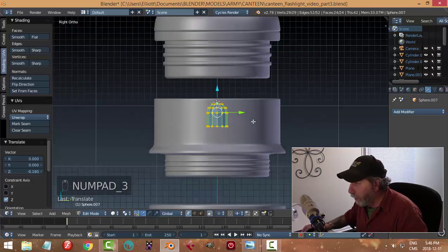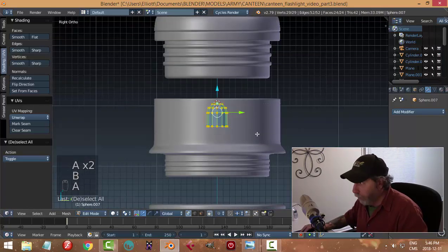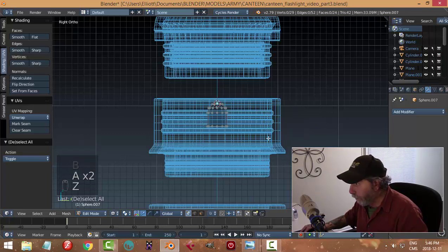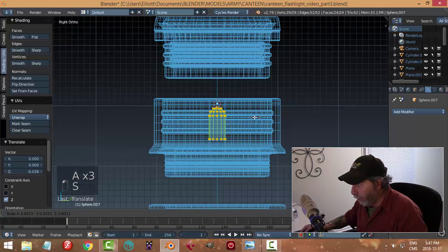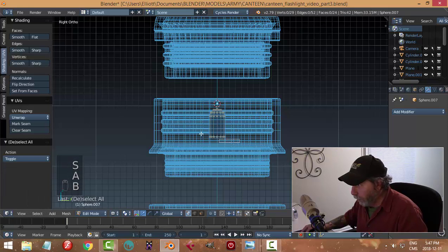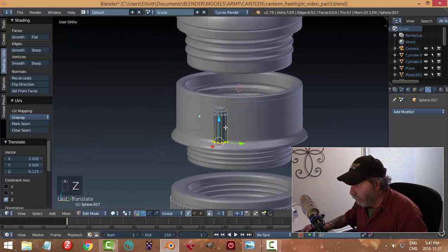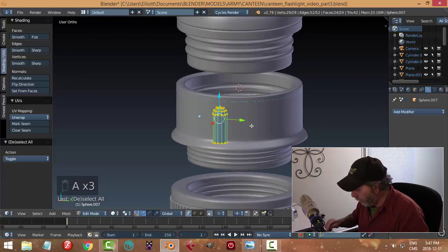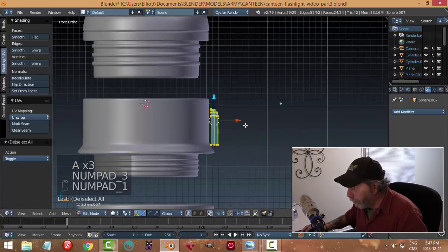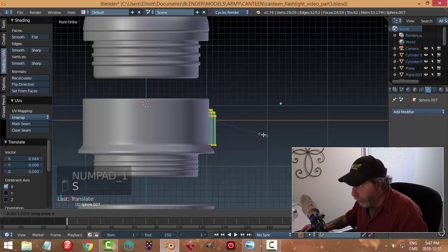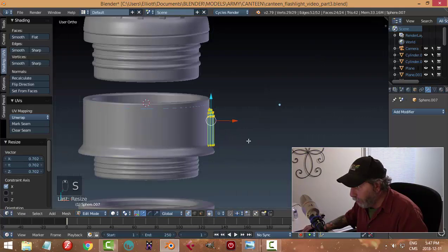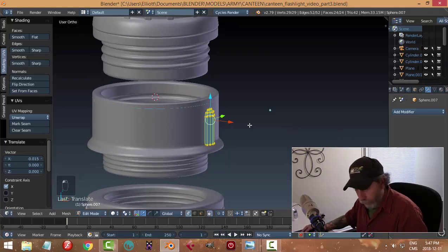And let's look from the side here. Let's make sure I get them all. So I'll go into wireframe, box select these. I'm going to pull them down again. To scale the whole thing down now, and just keep shaping this to the way I like it. Something like this. Let's get it again. Look from the front and push it in. Let's scale this in the X a bit, flatten it out, but I do want some of that curvature.